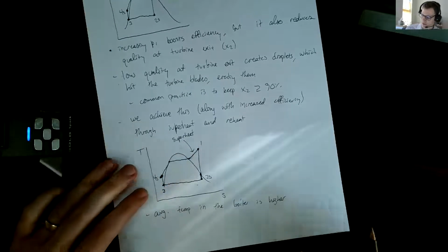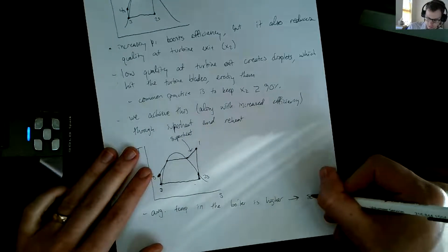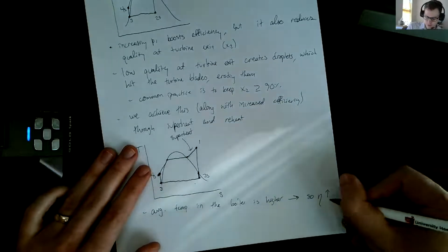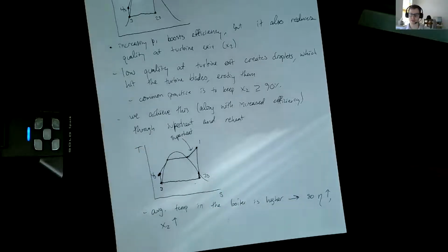Okay, and so we get two benefits out of this. The overall efficiency goes up, and the quality at the turbine exit goes up. It's a win-win. So we like superheating. Okay, this also changes the terminology a little bit.